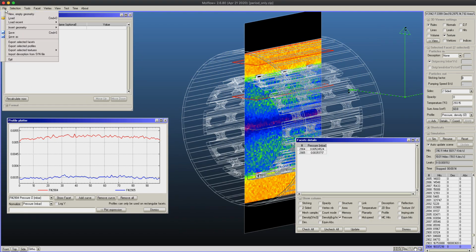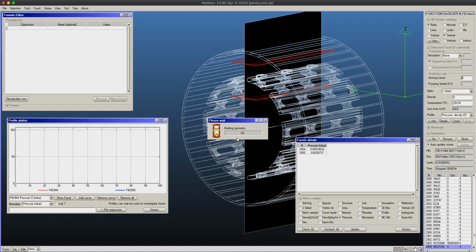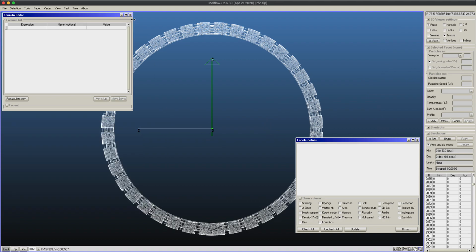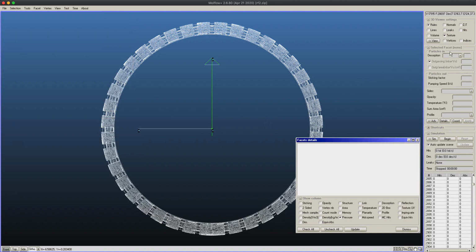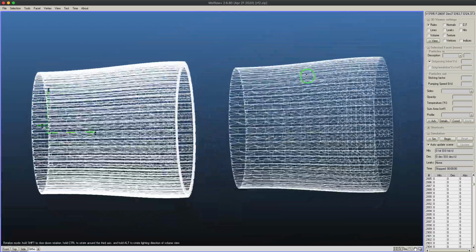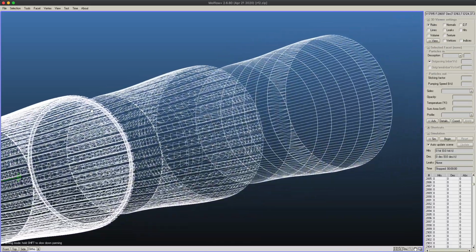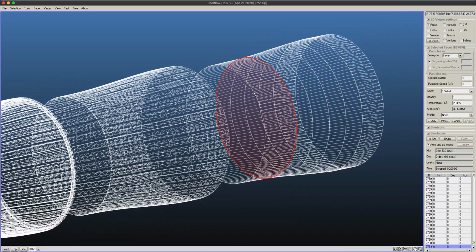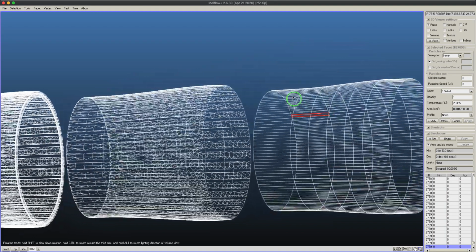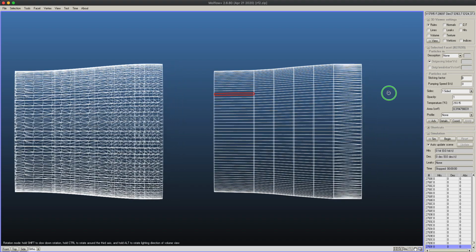Now I will go back and actually show you a few more difficult cases. So here I had an RF finger, which we are not going to solve this time. Here you can see how the fingers were. And I was recreating circles, and using the scale command I was trying to follow the shape. So if you look from the side, the diameters are matching the original shape.